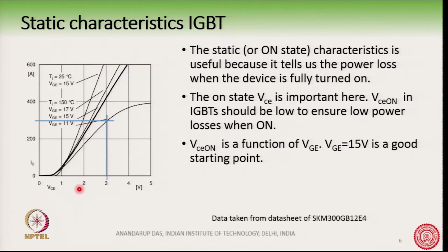Okay. And so, this gives us a clue that VGE should be sufficiently high, so that the VCE on should be low when the device is fully turned on, because we want to reduce the losses.